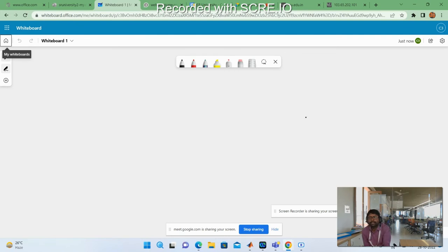So we are getting a steady state frequency deviation equal to minus 0.029. Now tell me, what is the system frequency? If you assume the initial frequency f naught equal to 50 Hz, what is your system frequency under steady state condition because of the 0.01 change in load demand, positive? What is the system frequency now?